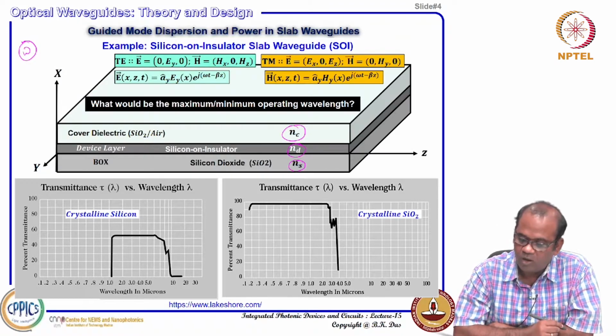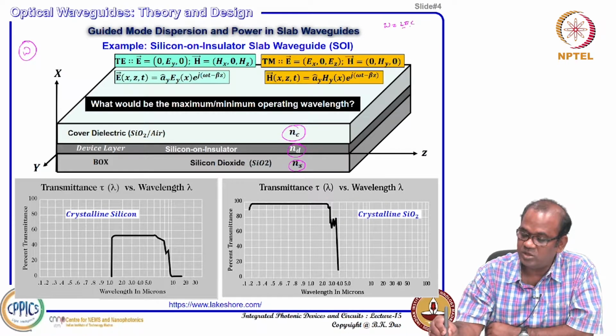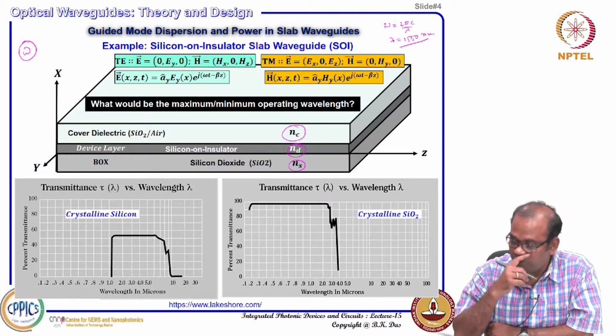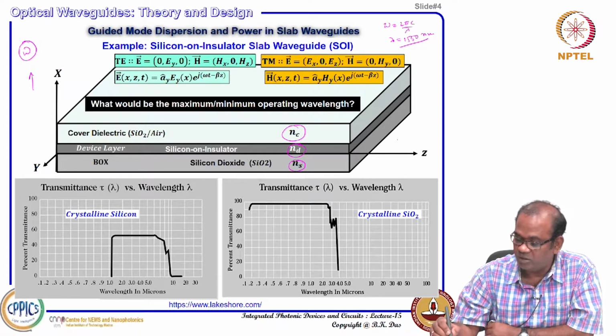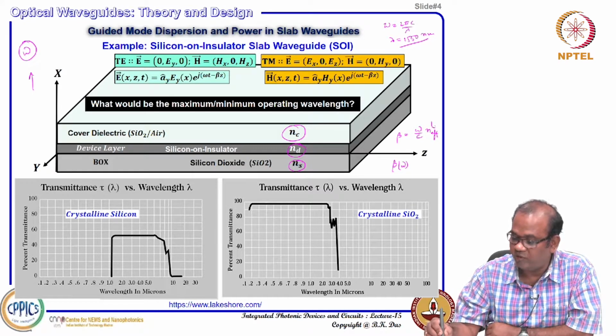use? Of course, we are interested around omega, defined by 2 pi c by lambda, with lambda equal to 1550 nanometer preferred. That is the third generation communication window, that is fine, we can use this. But if we want to vary any frequency, if I want to find out the relationship beta equal to omega by c times n effective, at different frequency what is the value of beta of omega, it may not be just proportional; effective index can also be